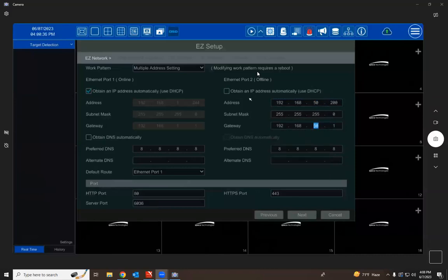So that way, when I'm doing a changeover, my secondary NIC card is going to be set to the same DHCP range as the existing cameras. Then it'll be more of an automatic recognition instead of having to go into each camera manually and switch them to match what range was in here by default.